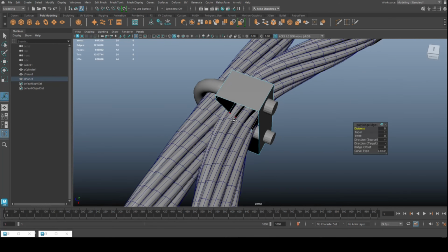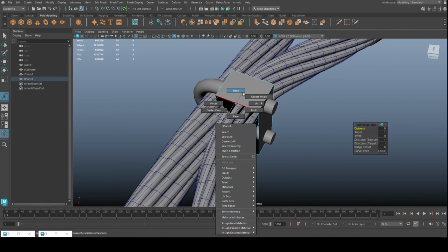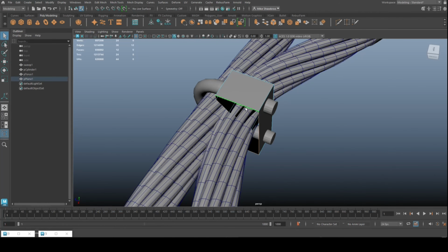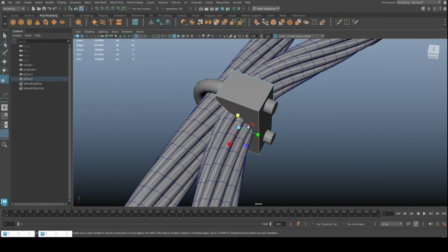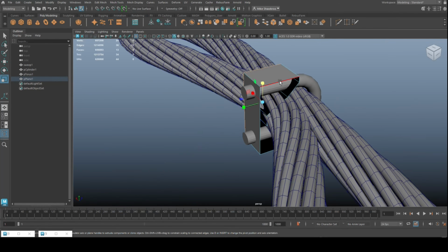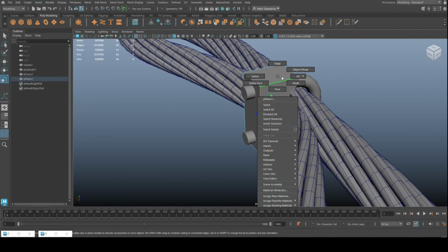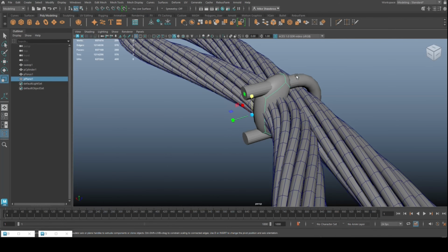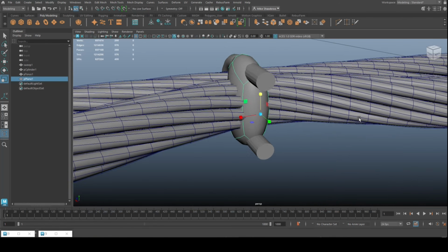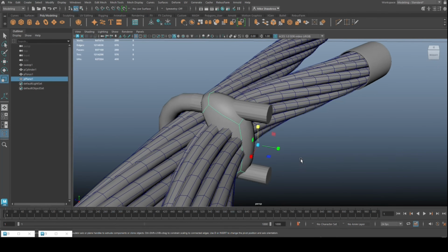I'm wondering whether that's necessary because we're not going to see this, so let me just give this a go. We're going to go to mesh and fill hole, and we'll double click right there, hit G to repeat. Then we're going to do a preview smooth, hit 3, starting to get there, yeah.